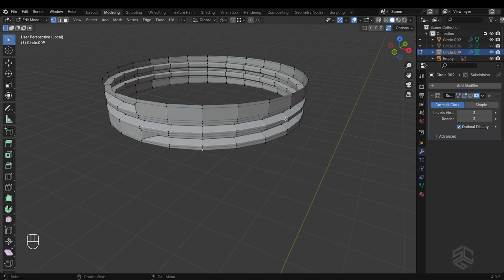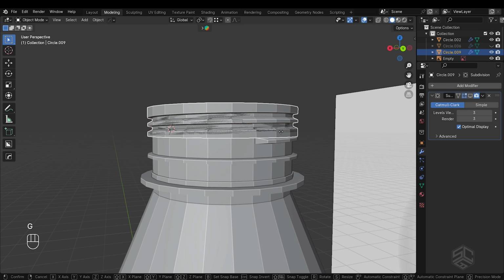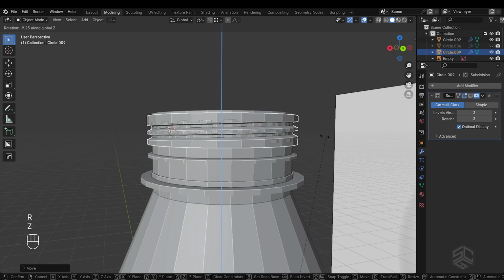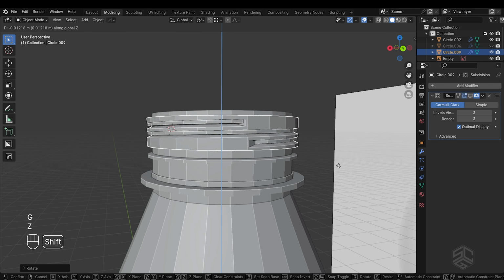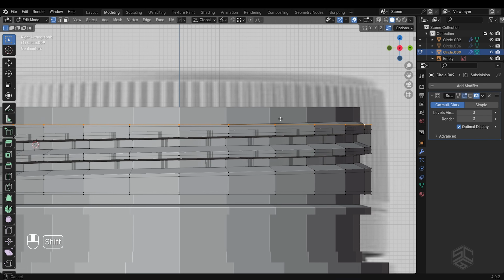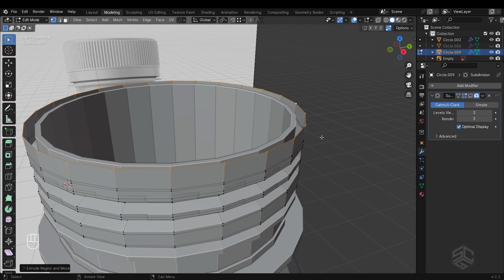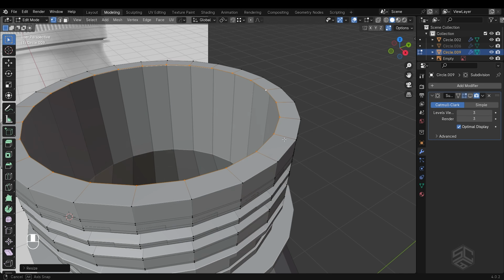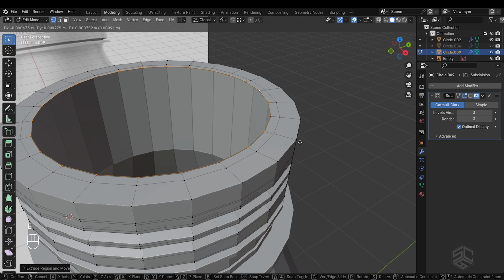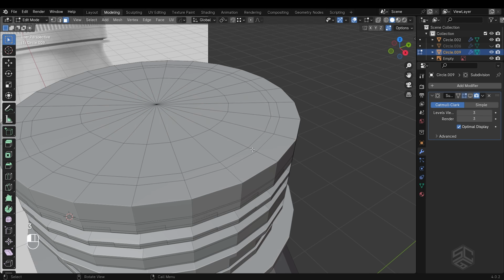Once you've finished modeling the shape, press / again to exit isolation mode. Move the shape slightly along the Z-axis and rotate it to align correctly with the bottle thread. Select the top vertices, extrude them to start filling in the bottle cap, then extrude again and scale inward. For the final vertices, press M and choose Merge at Center.